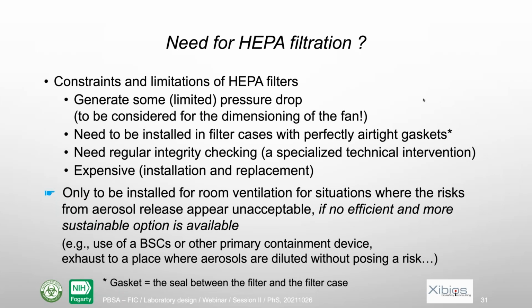So when you need to replace them, you have to pay for 1/3 of the price of the biosafety cabinet. So to me, HEPA filters only have to be installed for room ventilation for situations where the risk from aerosol release appears non-acceptable, and only if no efficient and more sustainable option is available.